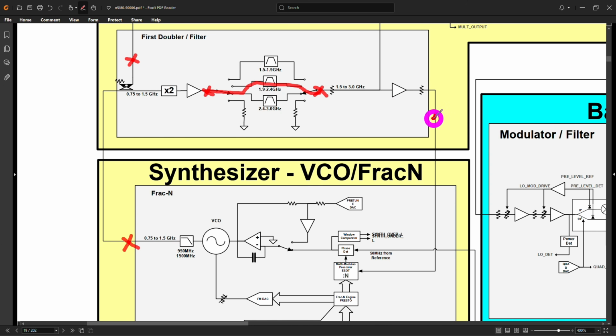And then we looked at the signal coming over here, which is the one that's going directly into the divider. And that one seemed to be okay too. Now, right around 1.9 gigahertz, when we were crossing that barrier, it became unlocked and the VCO frequency completely disappeared. Now, that happens to coincide with exactly this transition. Now, this doesn't necessarily mean that it's exactly at that frequency. That's something that we have to verify experimentally and see where these switches happen.